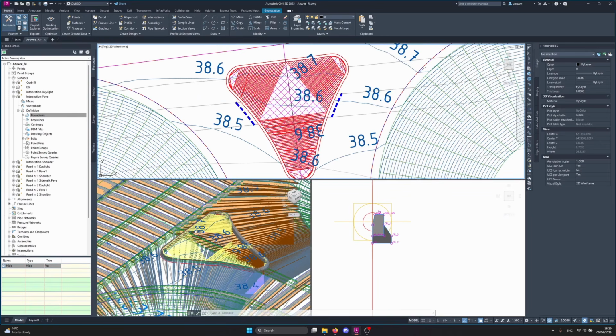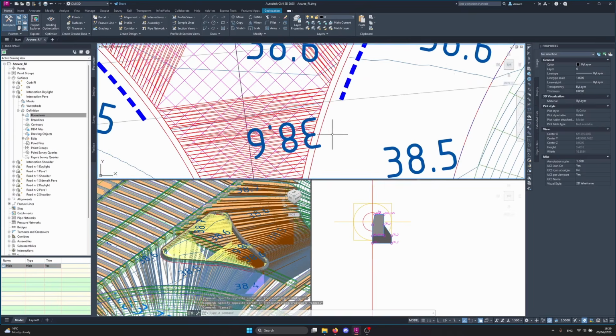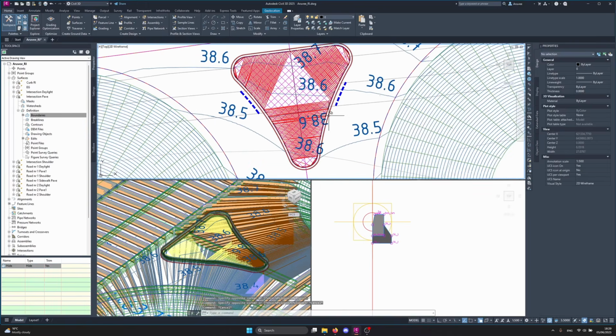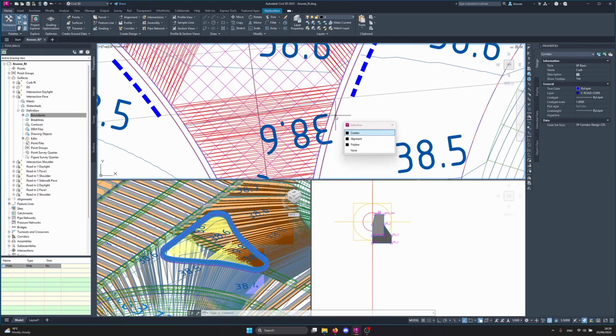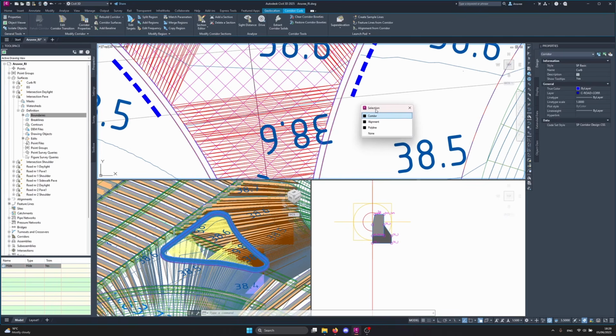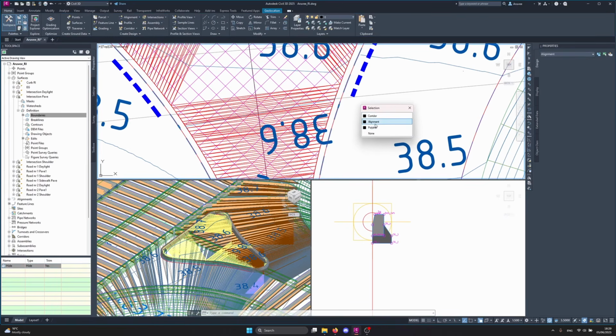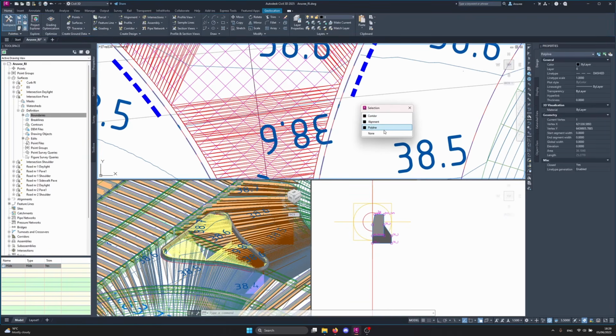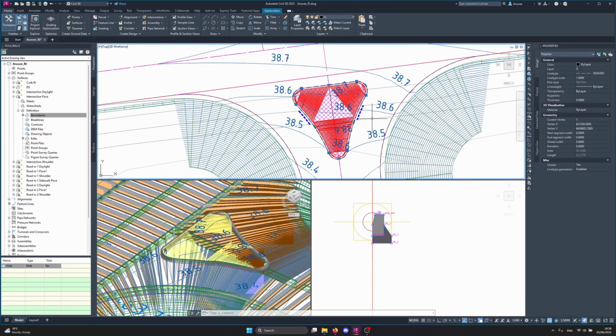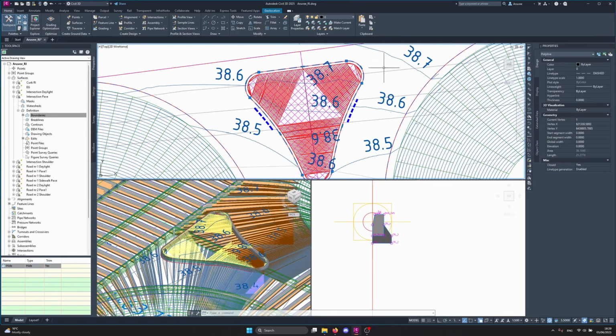As you can see, I have already made the island, so let me walk you through. Let's start from the outside of this island. Let me click right here. And as you can see, I have a polyline, an alignment, and a corridor. So let's get started with the polyline. This polyline right here is used as a boundary for the surface below it.